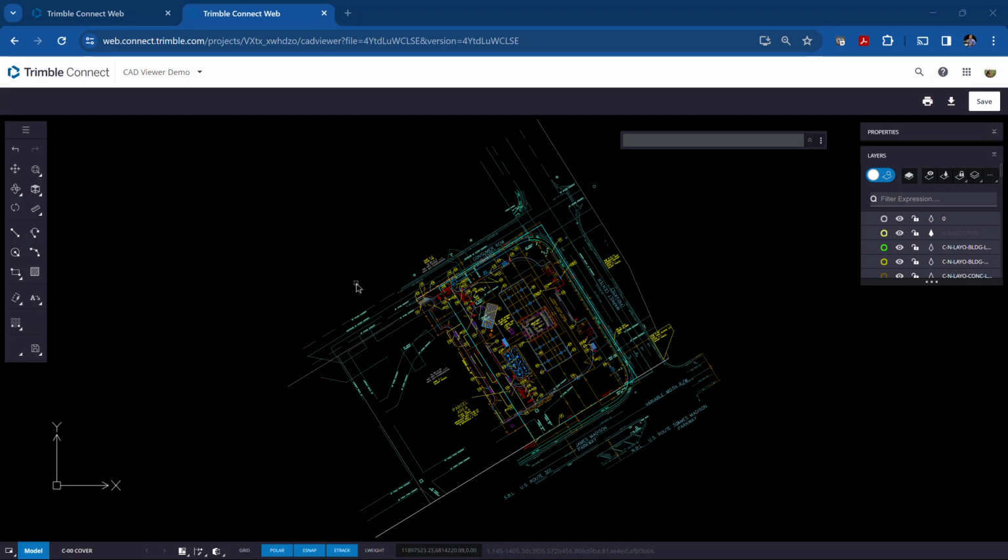So the first command we'll take a look at is the line command. We can access that by clicking on the icon over here, which says line, or you could use the command bar or command panel and start typing in line, and that will draw a line as well. If you hit escape, like I said earlier, it will get you out of that command.